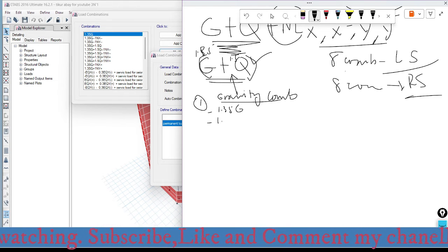And the second one is 1.35 times the permanent load minus 1 times the notional load in x direction. And this is the notional load in x direction, that is in x negative direction.